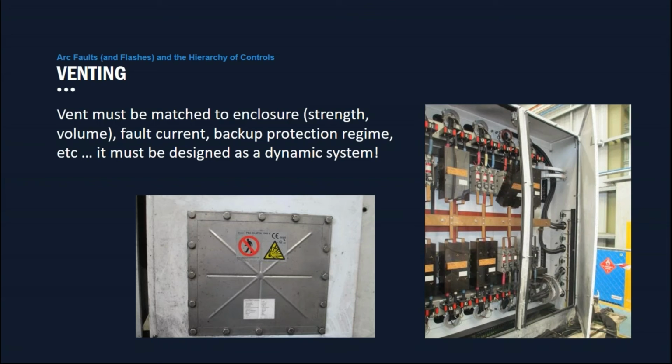So it is a dynamic system design, not a static system design. I've come across a number of instances where people revert only to static pressures. But of course, as we said, the pressure rise is proportional to time, and so these vents must open very, very quickly.